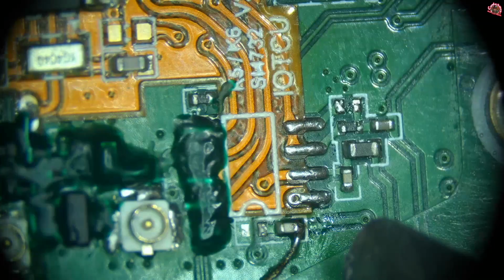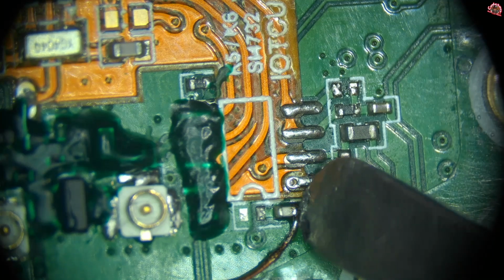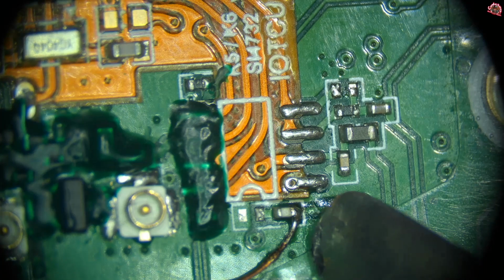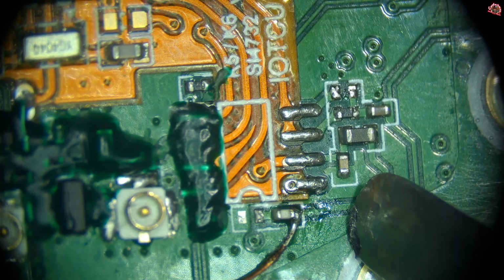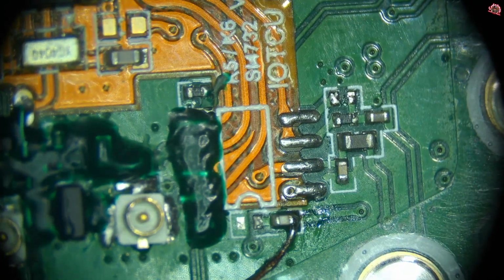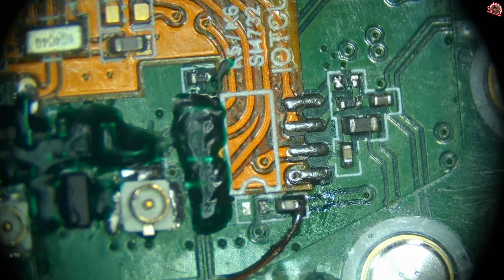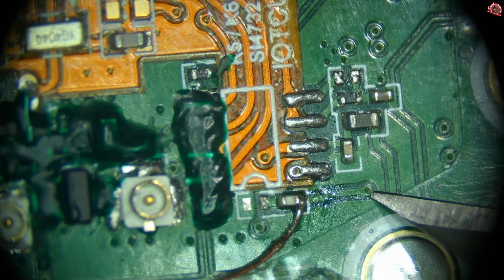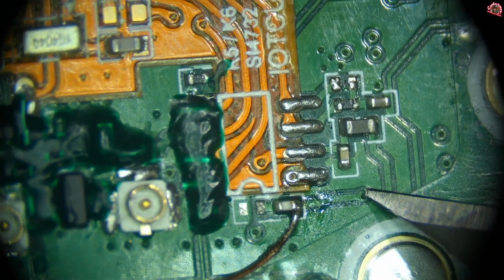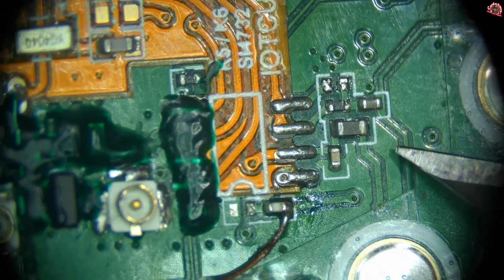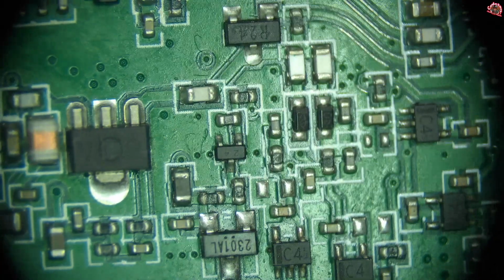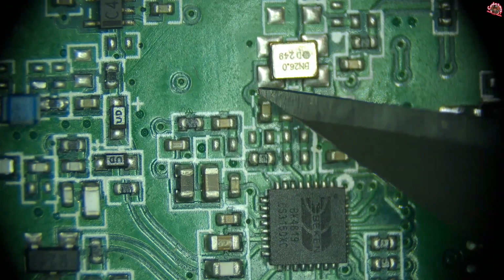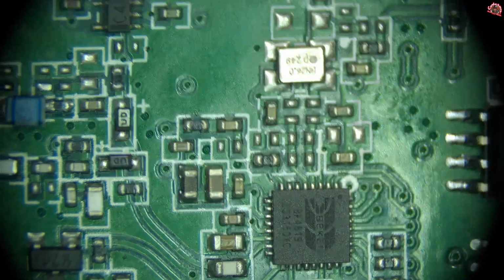But our SI mode, you see, we don't have a connection here. This is a no contact pin, so we do not need all this. Essentially, I can cut the trace right here. Let me take something more pointy. I could cut right here, but the signal still won't be here, and the signal underneath inside the board goes somewhere over here. So what I want to do, guys, is cut the signal right at the source, right over here. So that's what we're going to do.